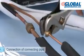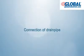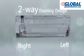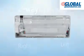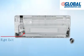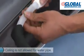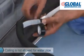Firstly, connect the low pressure pipe, then connect the high pressure pipe. Connection of the drain pipe. This series of products features a two-way drainage function, and the position of the drain pipe interface can be selected according to the installation position. Note that during the adjustment of the drain pipe, unused interfaces should be sealed with a rubber plug. Seal the drain pipe interface with adhesive to avoid loosening and leakage.